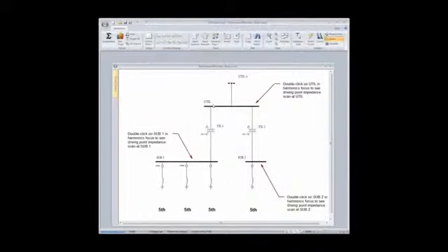So in this case, I've got a utility grid up here, and who knows what might be up there? Who knows what type of distortion levels might be floating around? Now, in most cases, the utility bus voltage has fairly low distortion. I mean, probably 1–2% is very typical. But you would be surprised that if you presented a low impedance path to the utility system for, like, a fifth harmonic filter, for instance, you may get very surprised at how much current you absorb.